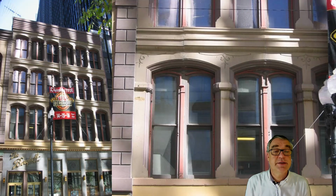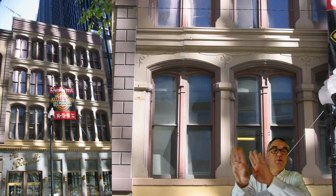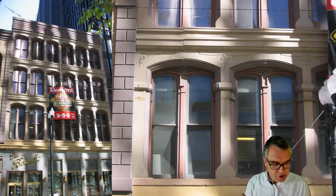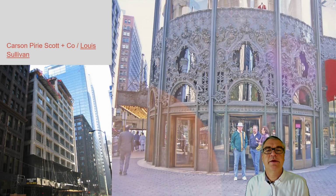Sometimes we see this. This is a concrete structure, and again we understand that this arch is supposed to take the loads down. It's a concrete structure, but when we look closer to it, we see there's a joint here and there's a joint here. So it's actually a T-section prefab component made in concrete, then connected to each other. This creates the entire structure. So there's some aesthetic which seems to follow a dead load structure to organize forces down. But when we dig into the technology, we understand it's a different technology, which just mimics a certain aesthetic, but doesn't really follow it as a technical solution.